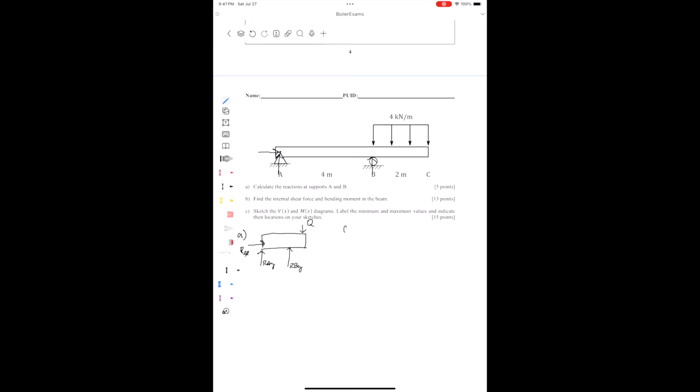So, in order to find the magnitude of the discrete force Q, it'd probably be better if I wrote out what the actual equation was. To replace a distributed load with a discrete one, the formula is the integral from x1 to x2 of your q of x function integrated over x.